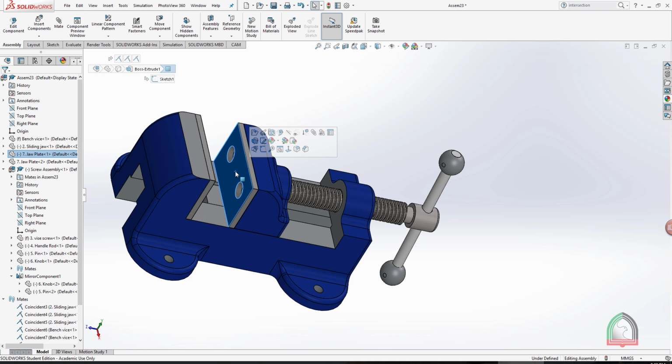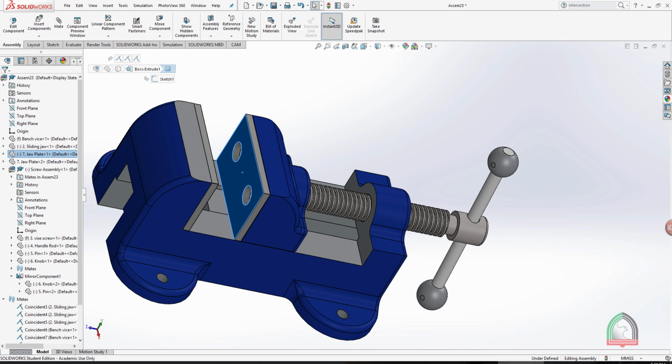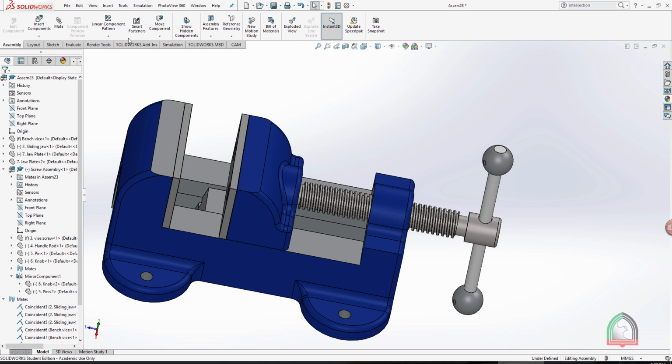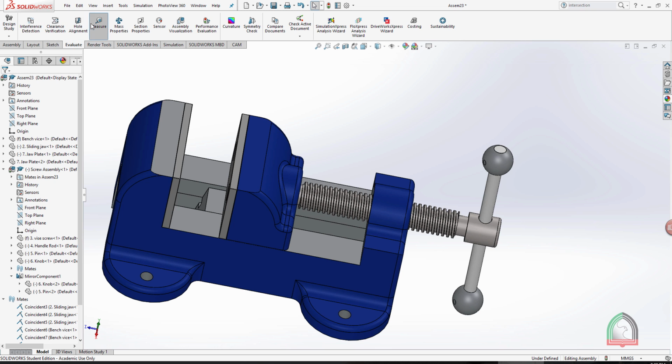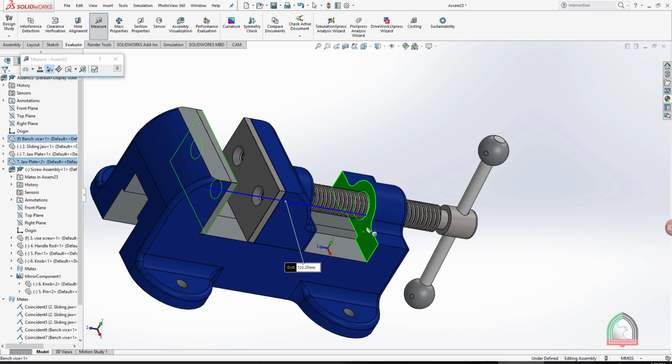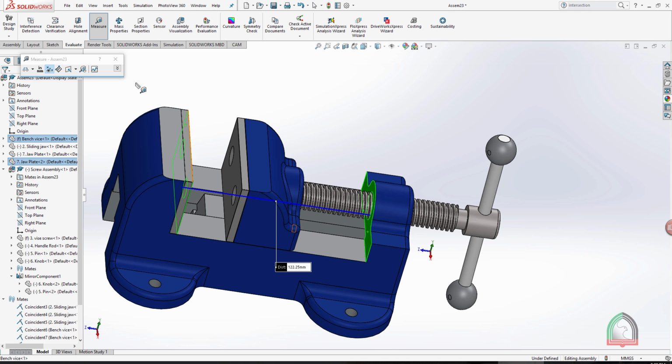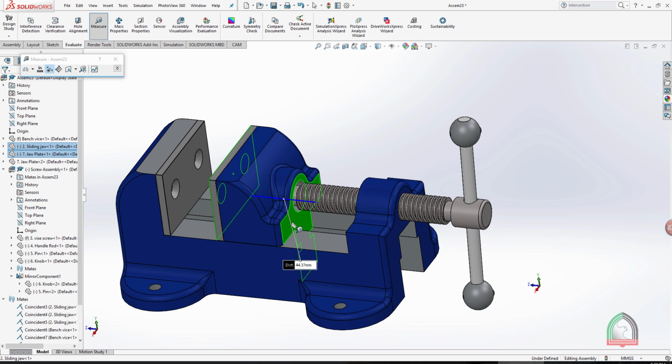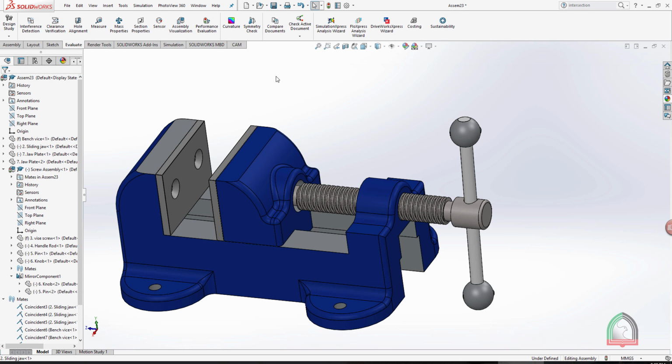So in order to know the maximum distance, what I'm doing is, see, the distance between these two is, go to evaluate, take the measuring tape. From this surface to this surface, the total distance is 122.25. But we need to minimize the thickness of this one. So I'm selecting the thickness of this one. It is 44.37. When we are minimizing this 44.37 from 122.25, it is 77.88. So we can give the limit now.